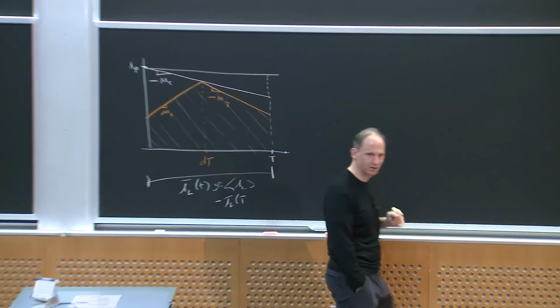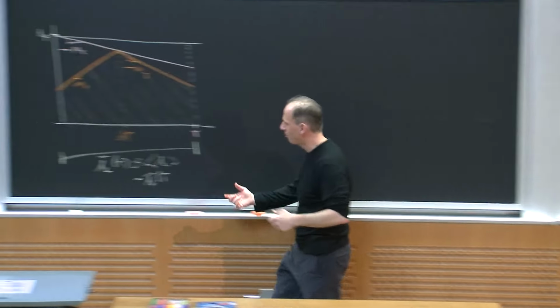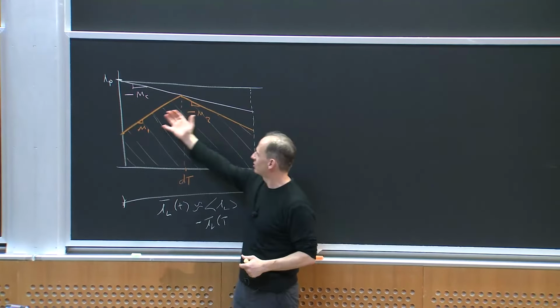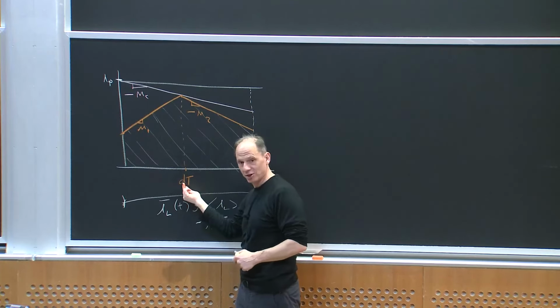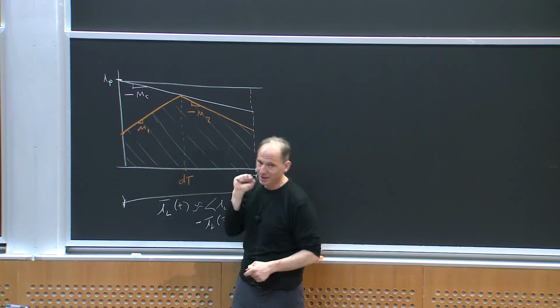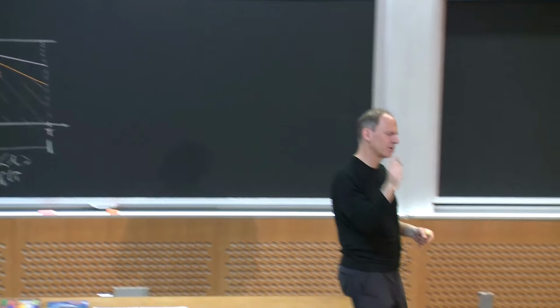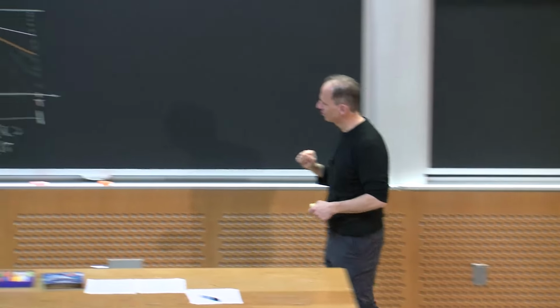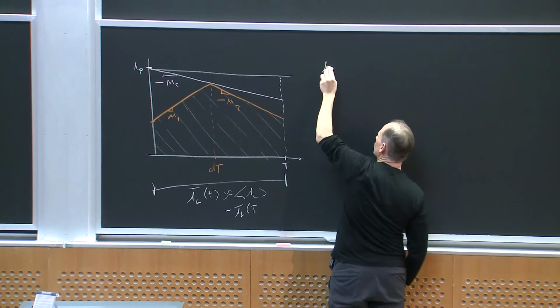But do people see the basic idea I'm going to use? I'm going to approximate iL bar as the average of this waveform, and then that's a function of the duty ratio in that cycle, and then I'm going to swap that into my local average duty ratio equations. Okay. Actually, I'm going to linearize it first, but that's neither here nor there. So let's do that. What is my approximation to iL bar?